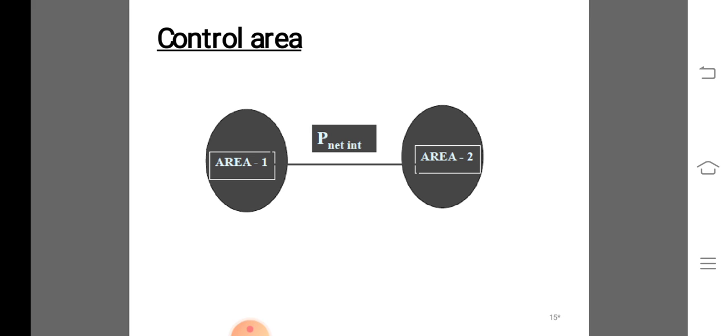If a frequency controller is placed at B, then it will shift the governor characteristics at B parallel to itself. The frequency will be restored to its normal value, reducing the change in generation at A to 0.